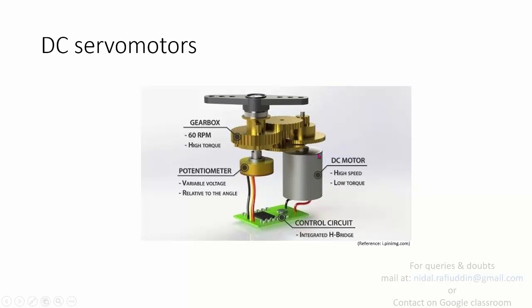This special motor accompanies a few characteristics, like it will have high speed and will be operating at low torque. So in order to change torque and speed, we'll be using gear trains. So it's a combination of the motor and the gear trains, then the output is taken from this jaw, and the displacement or the velocity or the acceleration is sensed through a potentiometer or any other sort of sensors. Nowadays we have other sensors as well.